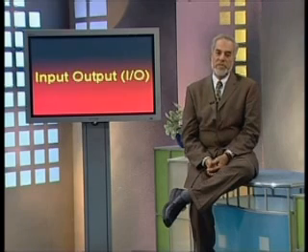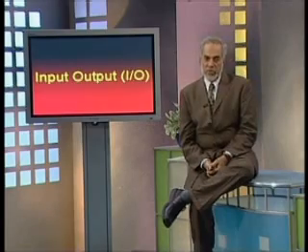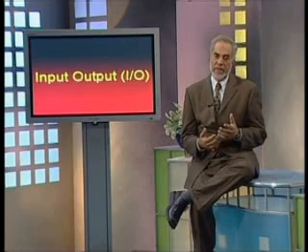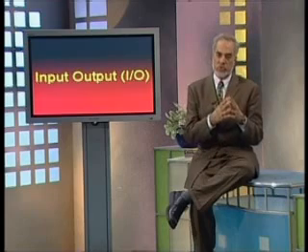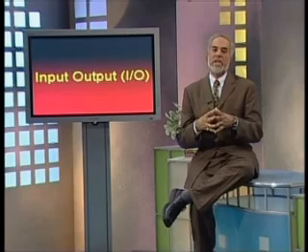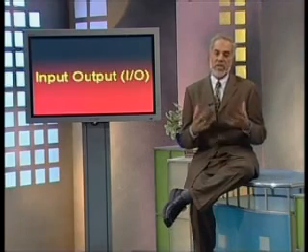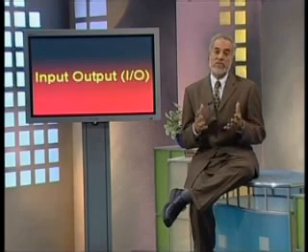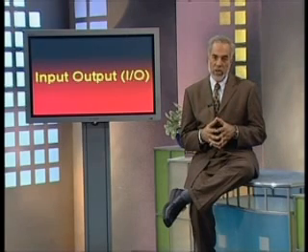We said that the simplest technique is a programmed I/O. The programmed I/O simply just goes through this concept of simple polling. That is, the CPU would scan and cyclically go through different I/O devices and check if it is ready or if it has got some activity or some interaction needs to be done. So the programmed I/O is very simple to implement. Nevertheless, its efficiency is pretty low.